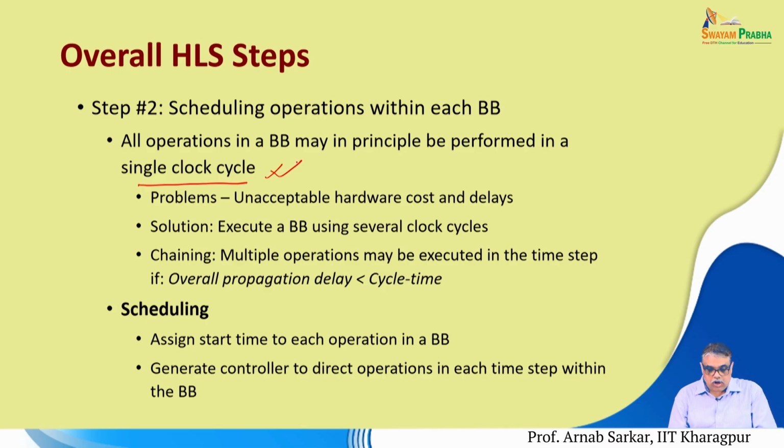Now, we also said that if we have that, the clock cycle will be arbitrarily long, which we do not want, because the same clock cycle will feed other basic blocks which could be smaller in size, and therefore, after completing their operations they will have to wait for a long time, because the length of the clock cycle has been chosen to be large. In order to avoid that, we have to embark onto the process of scheduling.